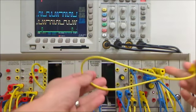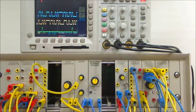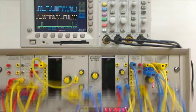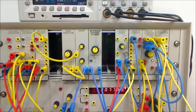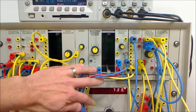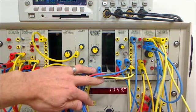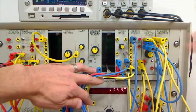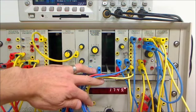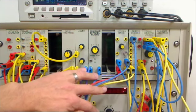We take the error signal, and if I lower the webcam, down here you can see the errors accumulating because it's not synchronized, and as soon as I touch the probe, the sliding window correlator synchronizes the local generator. We have no more errors accumulating, and we're now in a position to do bit error rate measurements.